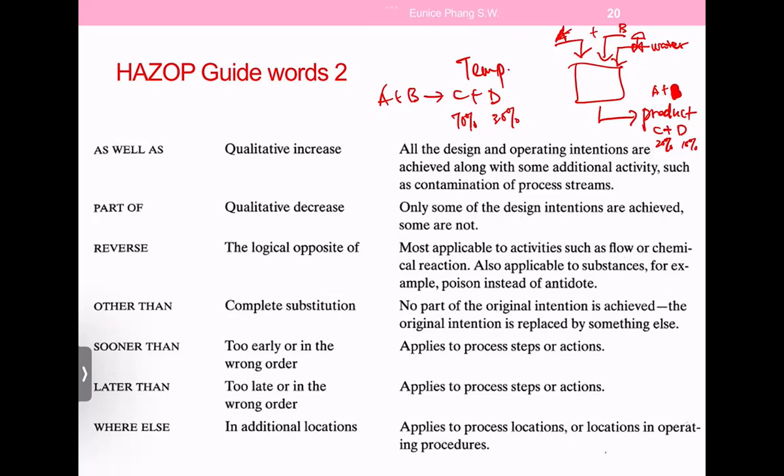Okay, so for all the things that can go wrong, you will have to brainstorm and then see how that happened, and what the consequences are when that happens. These keywords will help you start thinking, okay, there might be something wrong with the storage area, so what actions can I take, or what actions can my operator take if I'm sleeping and that happens at 2 a.m.? The operators look at that composition and say, oh no, I have something funny in here.